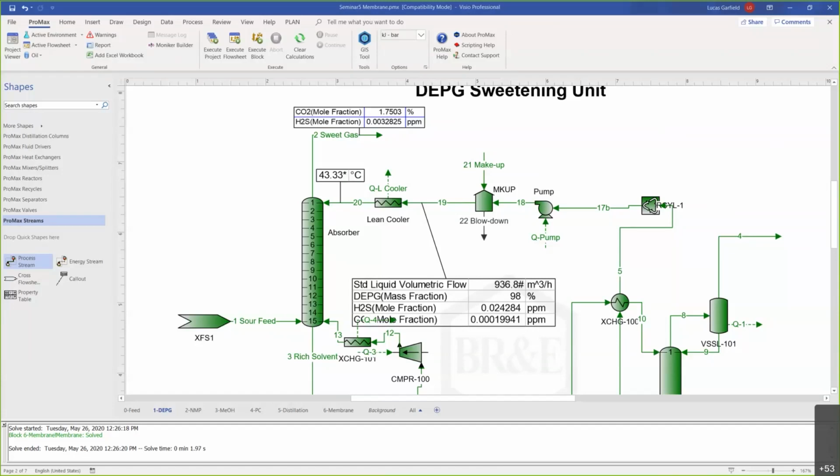remove. For flue gas capture, usually what we hear about in the literature is the use of primary amines. And previously it was always MEA. Nowadays there are some next generation primary amine solvents, like Mitsubishi has one called KS1, Shell has one called CanSolve. And those are also primary amines. Activated MDEA for flue gas capture, I'm not sure.